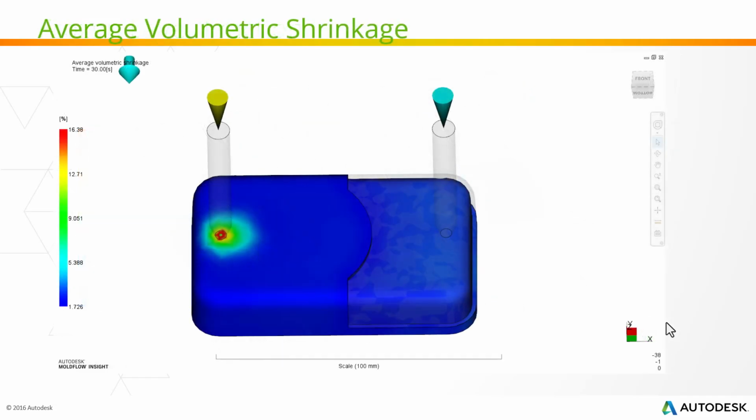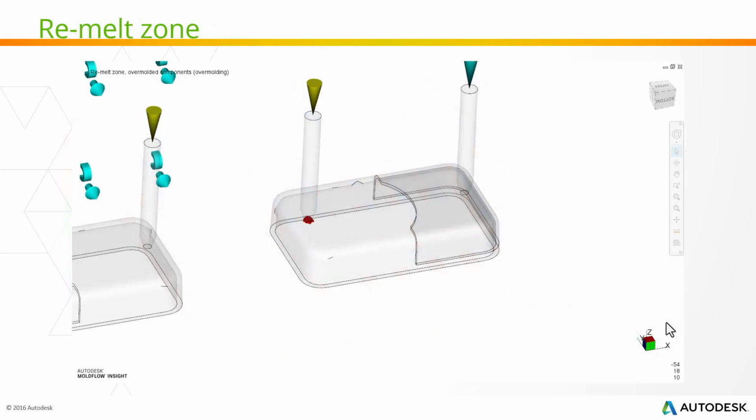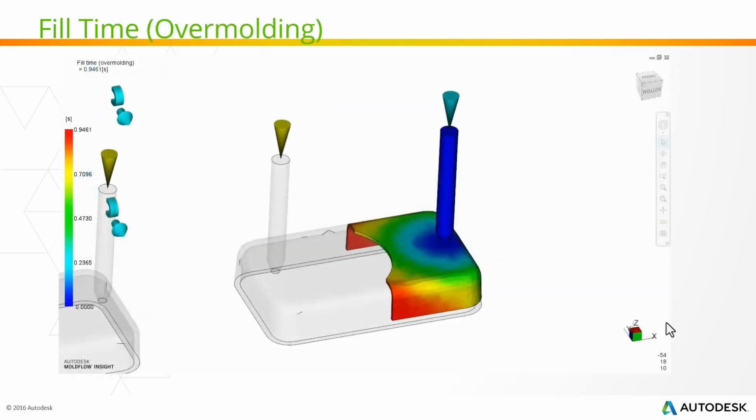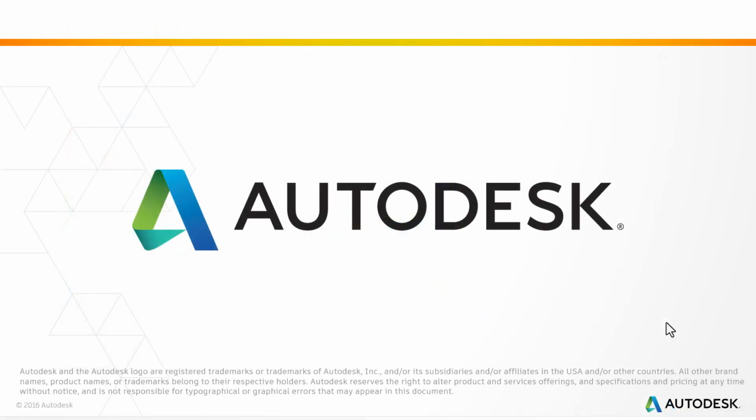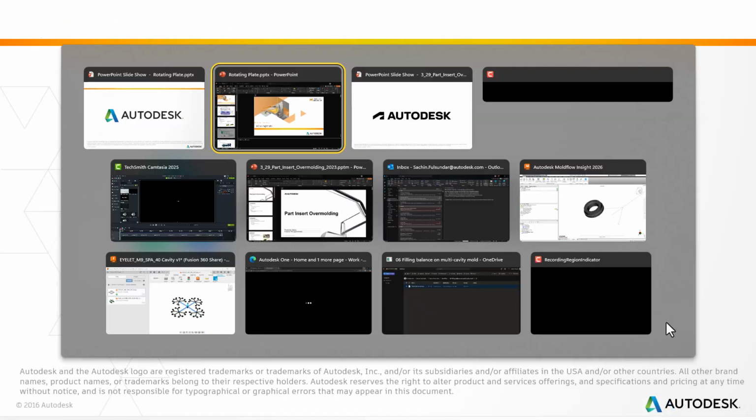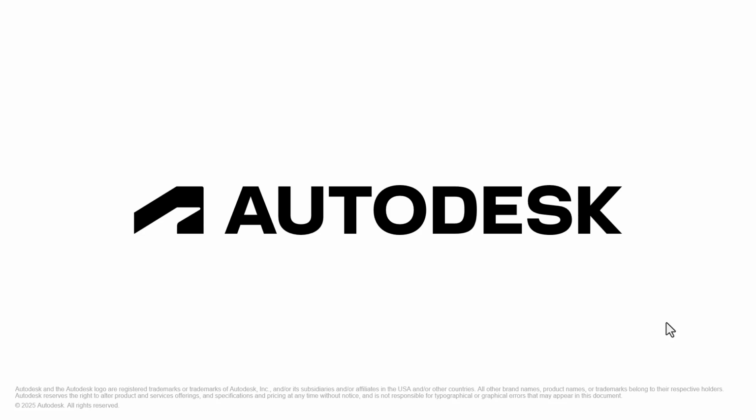So yep. And the one thing that I would recommend looking at is the remelt zone. Yes, you should remember that when you are doing an overmolding or a sequential two-shot overmolding, to have better anchoring of the two parts, you should have a sufficient remelt zone so that the anchoring happens perfectly in this case. That's the purpose of doing the overmolding. Let me show it if I have an example over here. Not really, but maybe next time I'll show you an example.